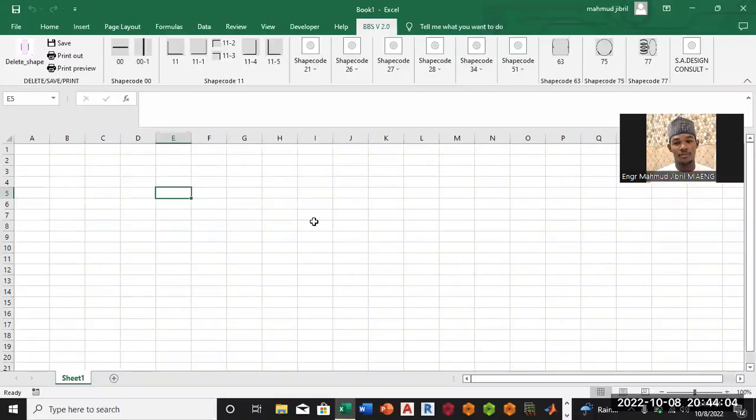So normally that is the method in which engineers transfer information from one place to another, or to the site engineers that are working on site, in order to know the quantity of the reinforcement that you are going to use. That is the normal simple way. When you just give a structural drawing without any bar bending schedule, many engineers, contractors, surveyors, and others will find it difficult to estimate the quantity of the reinforcement. So in order to estimate the quantity of the reinforcement easily, the bar bending schedule comes into account.